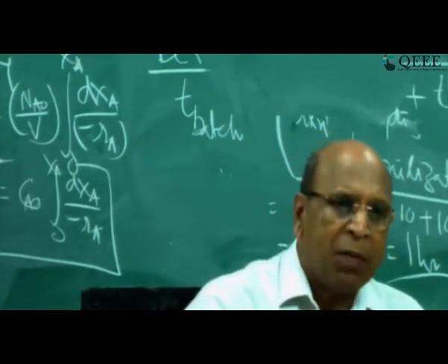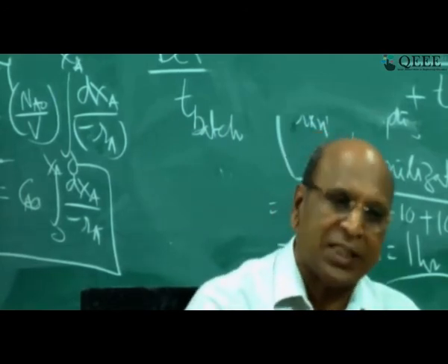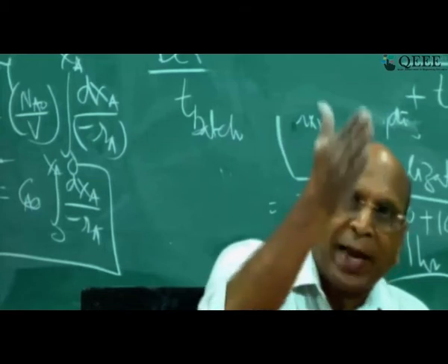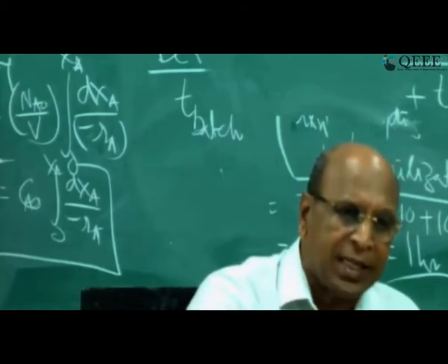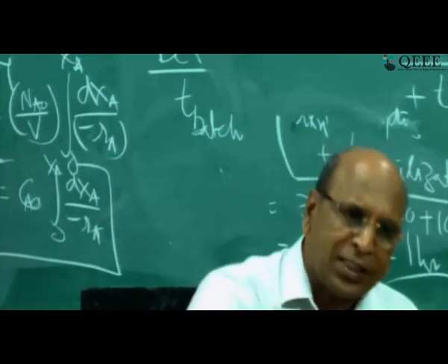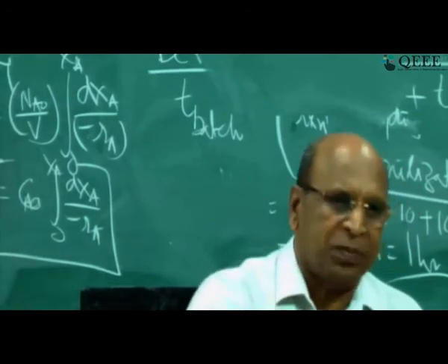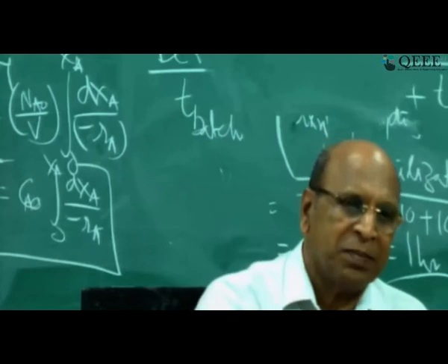And very commonly 3-inch tubes and 4-inch tubes are used in the industry. So that is why maintaining radial profile is very easy if the diameter of the pipe is reduced. If it is 1 inch, it is still very easy. If it is 6 inches, okay. But no one goes even beyond 1 foot as plug flow reactors.